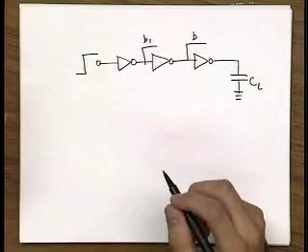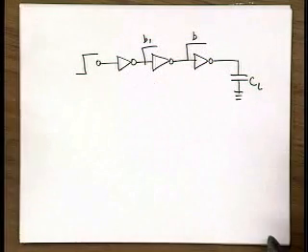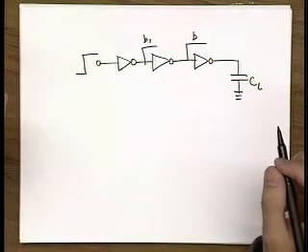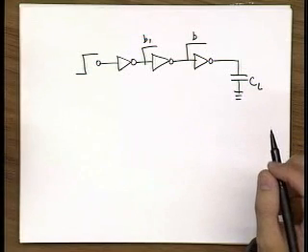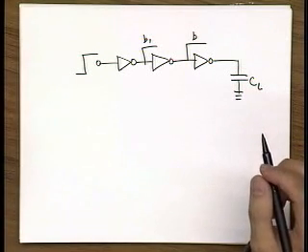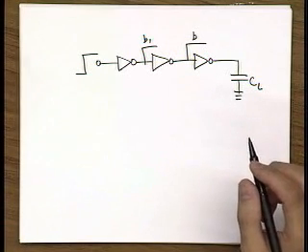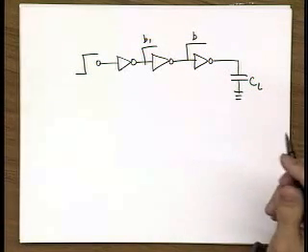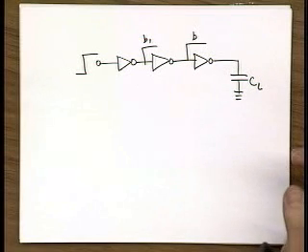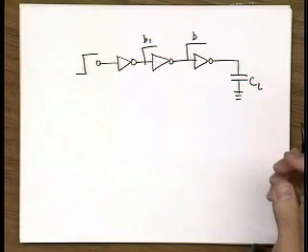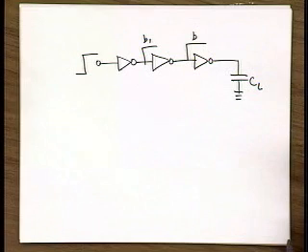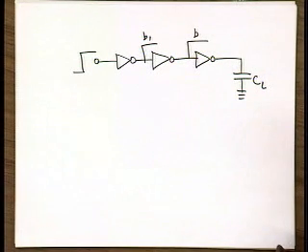And I think some of you actually pointed out some pretty good questions from the lab when you tried to simulate your unloaded inverter, extracted and also loaded with 50 femtofarads, and you were trying to estimate the intrinsic capacitance by measuring the delay of an unloaded case and the delay of a fully loaded case. And then you ended up with something pretty unbelievable. For example, that the intrinsic capacitance was about 50 femtofarads.